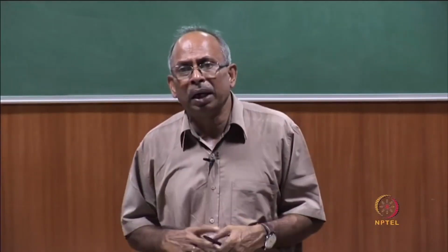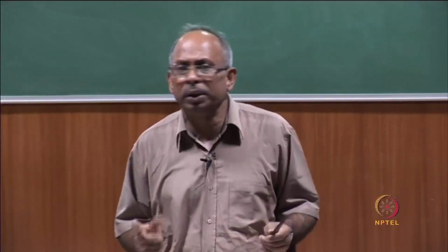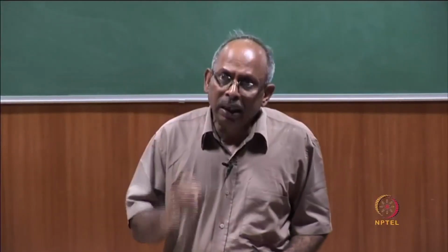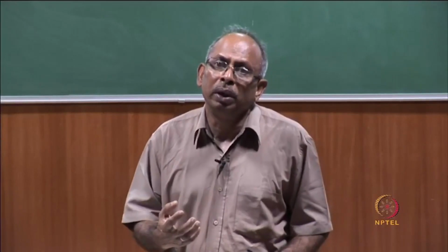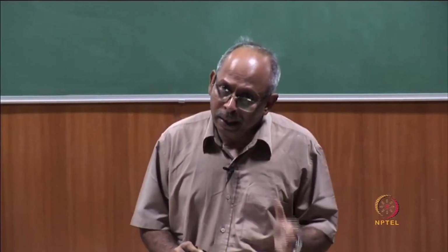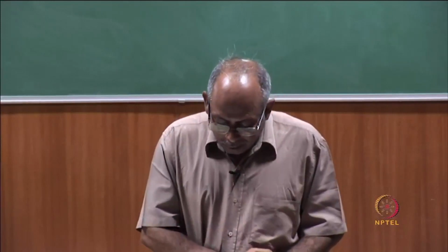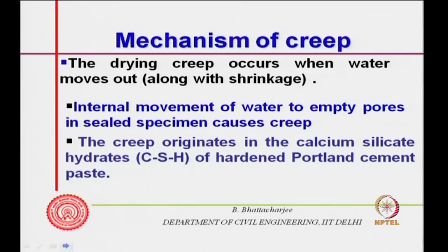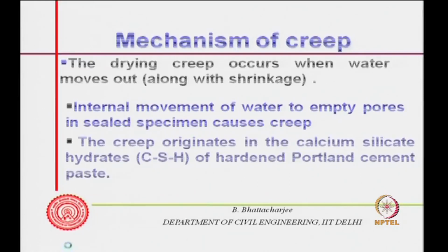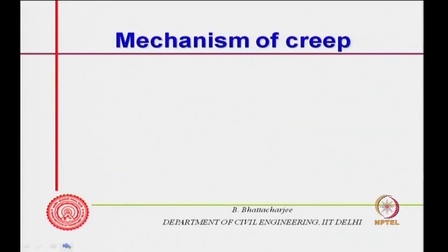One can list a huge number of observations that have been seen in the laboratory, but generally it is attributed to movement of water and the adsorbed water and so on. Basically, it is the calcium silicate hydrate, C-S-H, of hardened Portland cement, and that's where it originates.